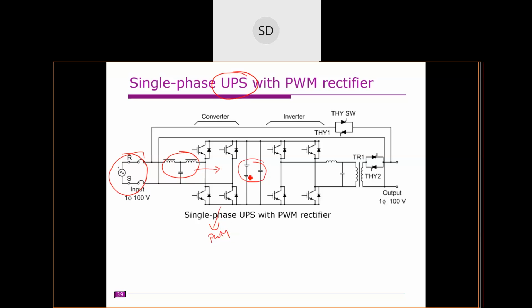We have two different types of UPS, online UPS and offline UPS. And this is DC to AC conversion, and it is feeding this load. So we have this rectifier and inverter, and their jobs will be interchanged if this AC source is not there. In that case it is fed from the battery only.